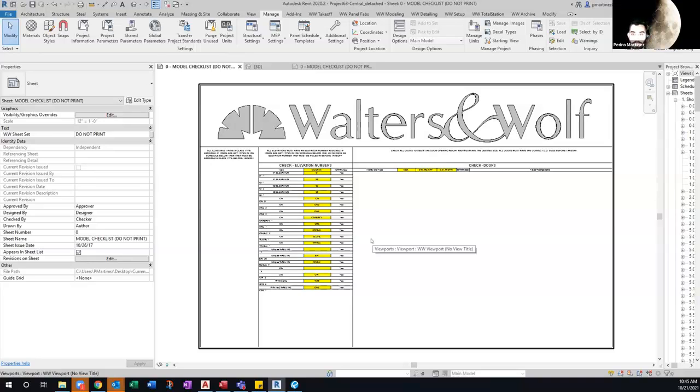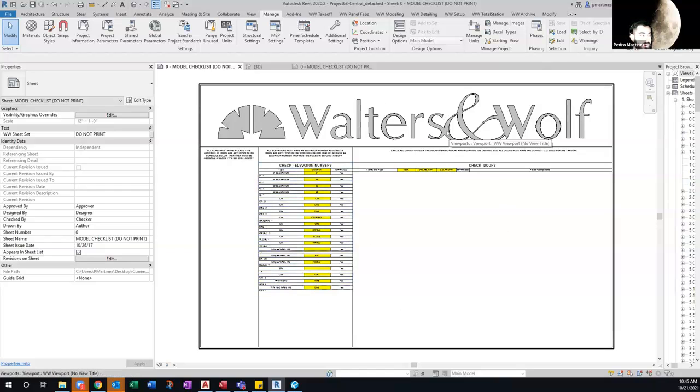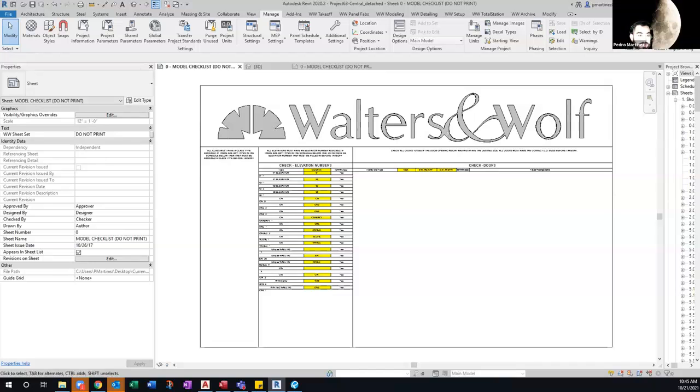This is something that we would probably check during our setup stage and takeoff, because the main one that helps us, like I said, is that the glass tags are not to the edge of glass. They are done to the DLO, which then drives our dimensions on our unit assembly drawings to give us the correct width of the mullion, if it's a jam, 2 3/4 typical. So just wanted to show and tell a little bit on what that is.